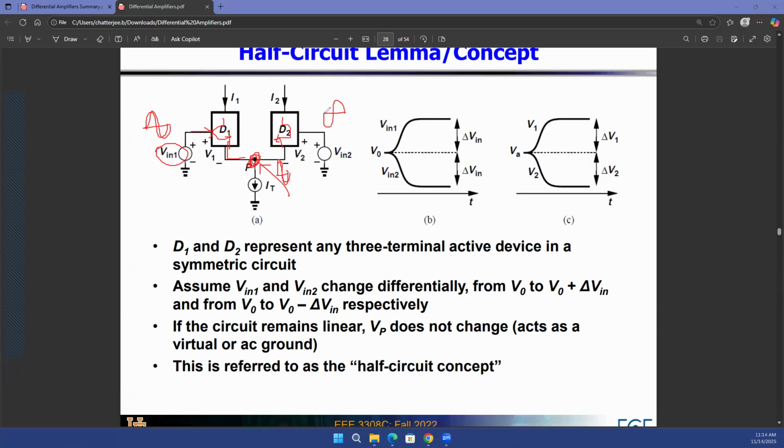But at the same time, I'm applying a V2 on the other transistor, the right-hand side transistor. And I should expect at the source of that transistor the same voltage that you're applying at the gate of this V2. So at the terminal P, this common source terminal, you should also see the negative sine wave at the same time. Now apply your superposition principle.